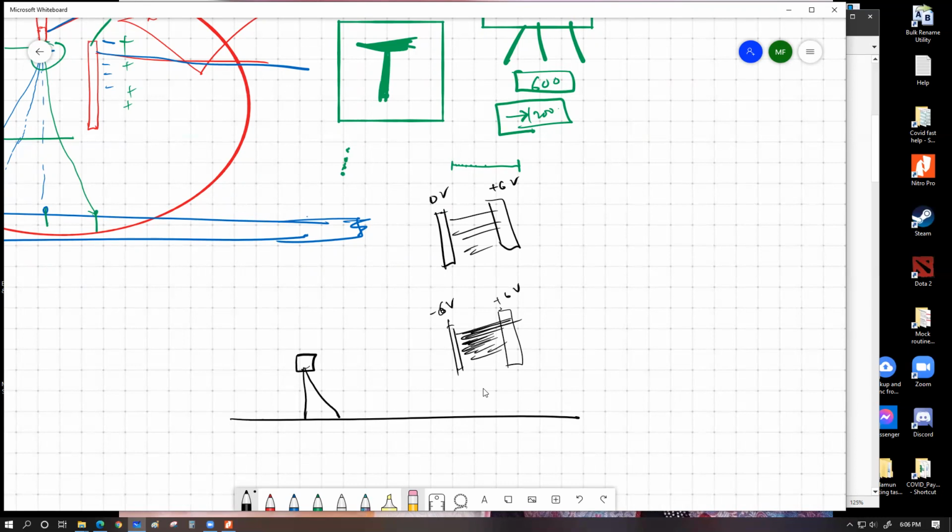Do you understand what I'm saying? Yes, sir. If we apply more positive voltage, you can bend it further. If we have low positive voltage, you can move it less, but you can only move it in one direction. Whereas if we have both opposite charges, the ink droplet might be able to bend in both directions. So if you have both directions, you are going to require fewer nozzles to cover the entire page. But if you have only this much space, you're going to need more nozzles. You have to have more nozzles, right? Yes, sir. So that essentially is a design consideration which makes the manufacturing and also the cost significantly less.